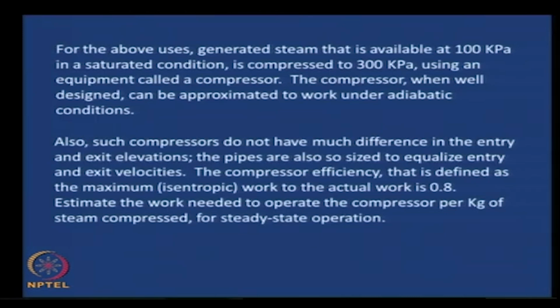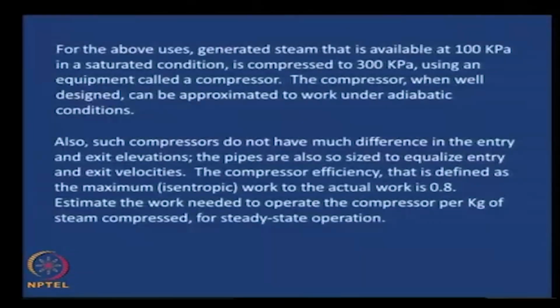Also, such compressors do not have much difference in the entry and exit elevations. Okay, Z_O and Z_I, there is not much of a difference. The pipes are also sized to equalize entry and exit velocities. Therefore, u_O equals u_I.